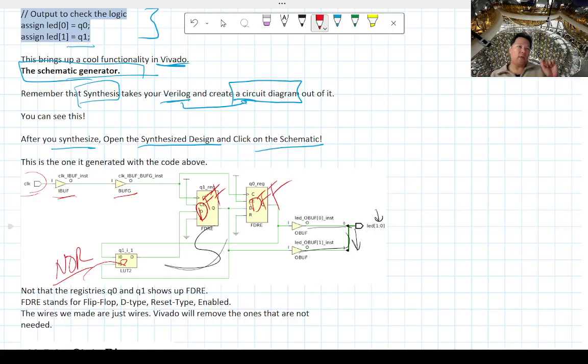That means the buffer actually holds that information for one clock cycle. So even though the oscillator can be going up and down at whatever speed, each clock cycle is going to hold that. In this case, I think it's 10 nanoseconds because you have a 100 megahertz clock.